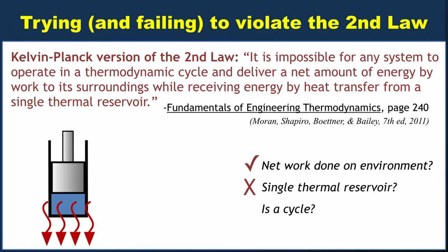So, not a single thermal reservoir, you actually need two different reservoirs to do this, and then it's a power cycle, no problem. And of course, we know that we passed the last criterion because we set up the problem that way. So, part of your job over the next week will be to look at systems like this and figure out how they violate the second law. Sometimes it's obvious, sometimes it's a little more subtle.